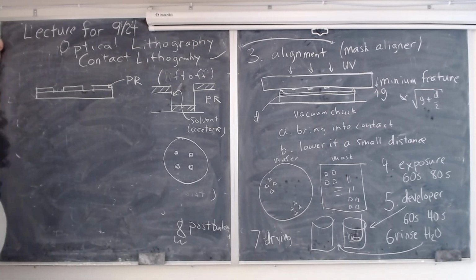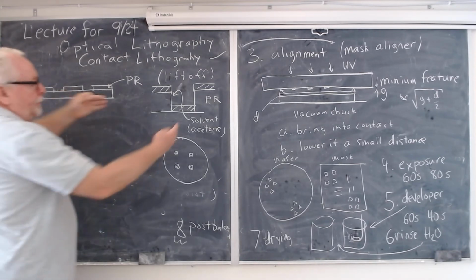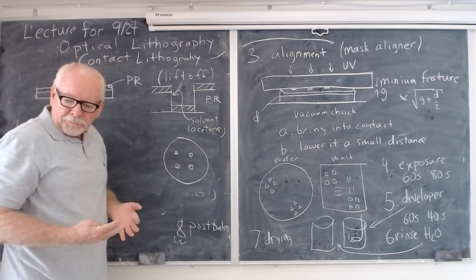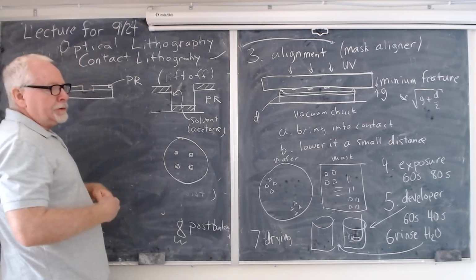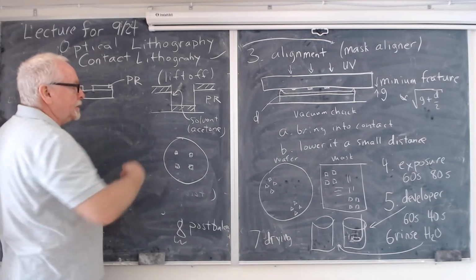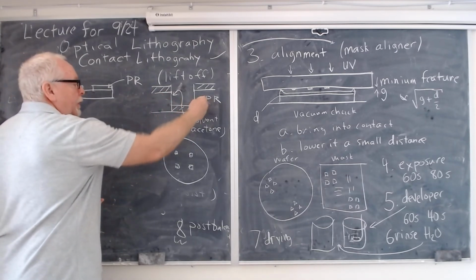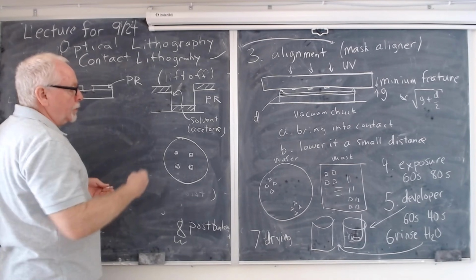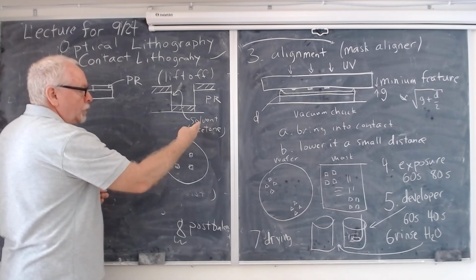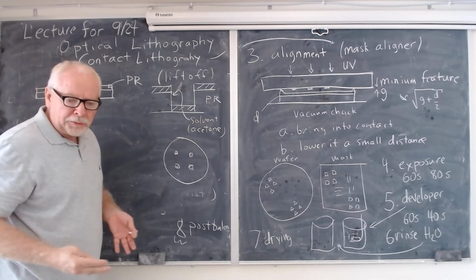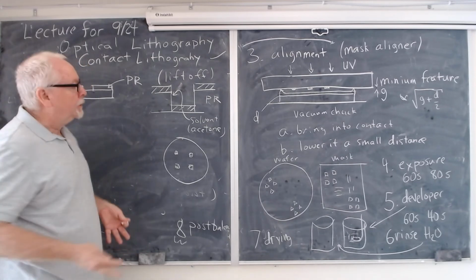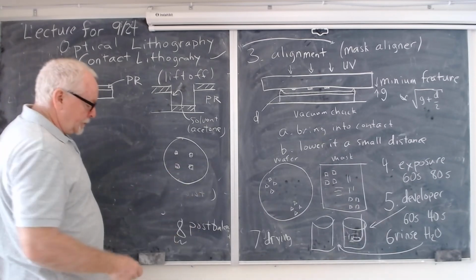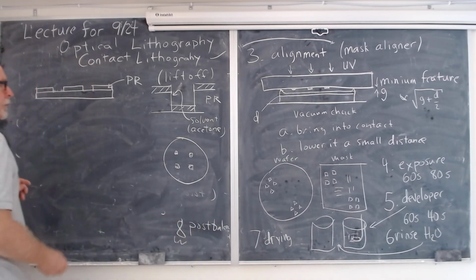The reason why is because the photoresist is just there mechanically. It's not resisting anything. It's just being there. In fact, you want it to dissolve very readily. You want it to be very chemically unresistive, so to speak, for the liftoff process. So you don't do step 8 for liftoff.